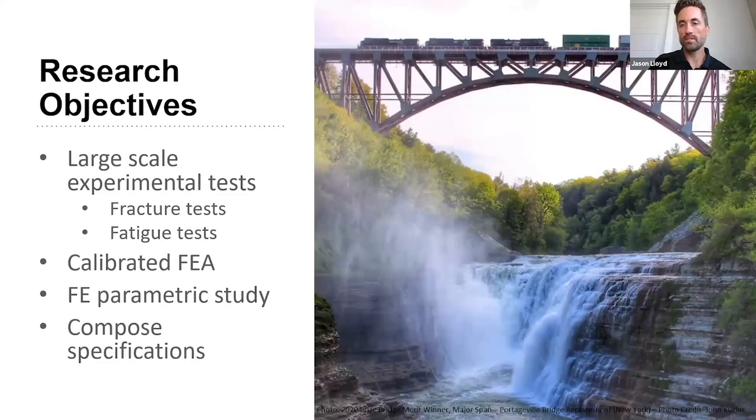The primary objectives for the research included experimental testing to determine if a running fracture could propagate across component boundaries, experimental fatigue testing of specimens in the faulted condition, meaning having a single component fractured, to determine the after-fracture fatigue life of the remaining cross-section, calibration of finite element models to support a parametric study needed to develop amplification factors that account for local stress concentrations due to load redistribution, as well as to quantify any secondary effects. And then finally, proposed specifications that were submitted to the AASHTO T14 Committee on Structural Steel Design for balloting and adoption.